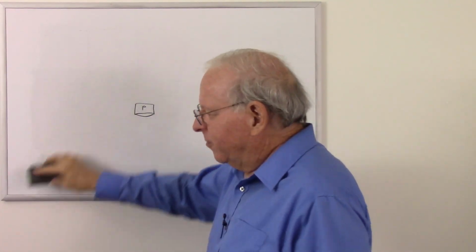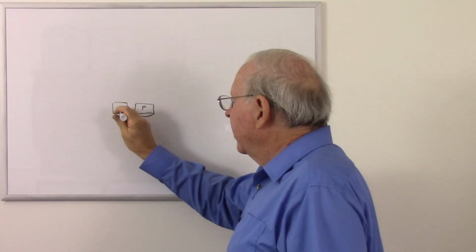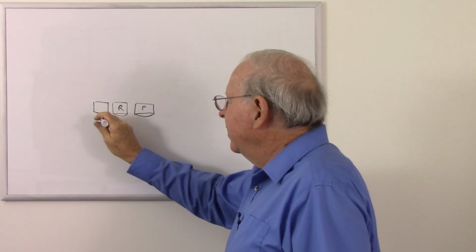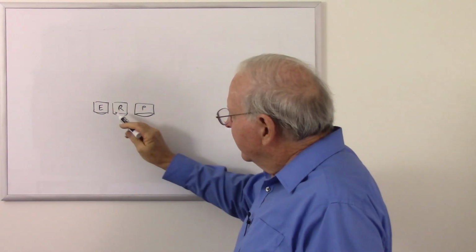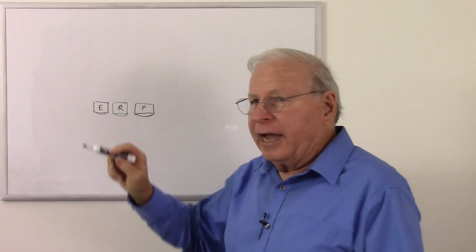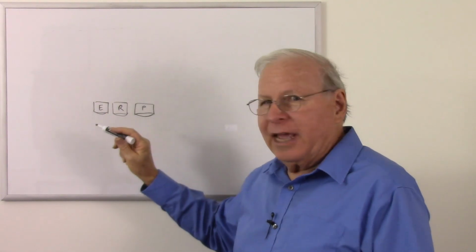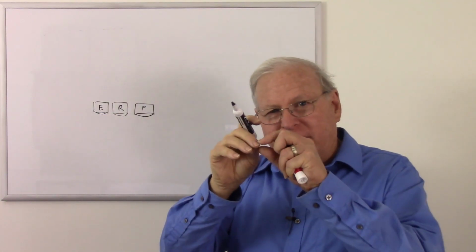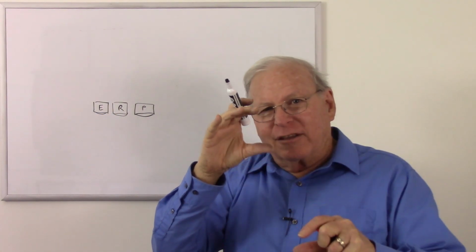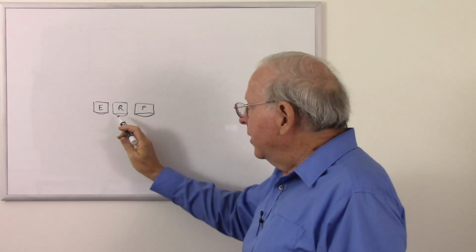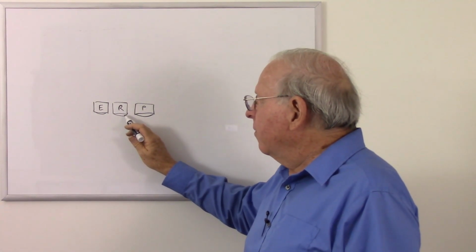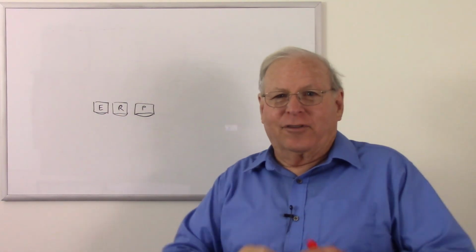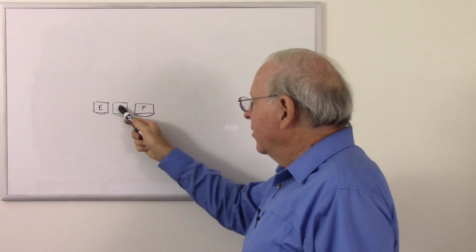So your better systems would have 3 heads: record head, a playback head, and an erase head. So what did the erase head do? You just simply sent that bias signal to it, and that would erase the tape before it got to the other. So we have that AC on there. As the tape goes by, it gets magnetized, but as it passes by the gap, the magnetization gets less and less and less, and you end up with an unmagnetized track going by the record head. And so your best decks would have 3 heads. So they're advertised, 3-head deck. So erase, record, and playback.